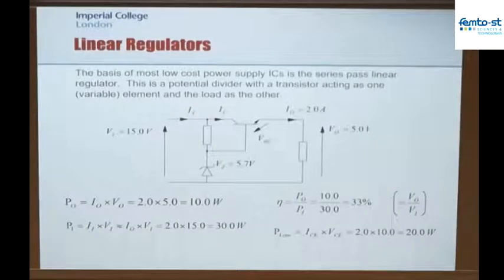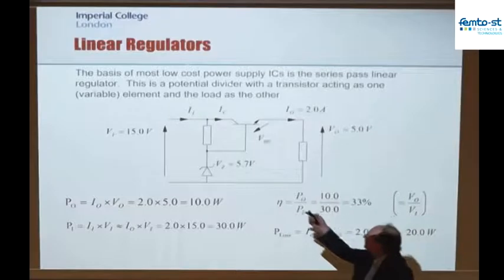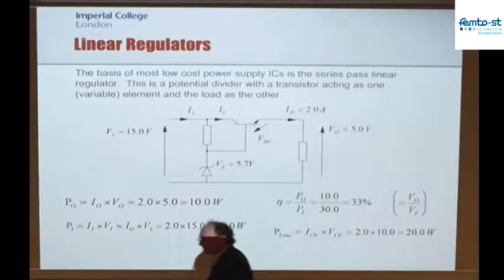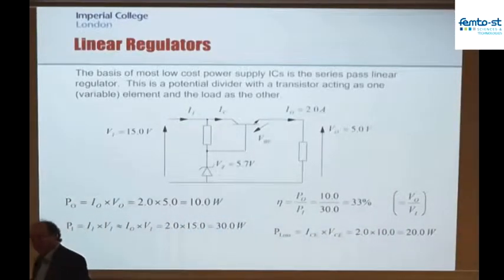So this circuit here is what we would call a linear regulator. And if you look at data sheets for electronics, if you build a piece of electronics, you'll see this. If you look at RS or Farnell or Mouser or DigiKey, wherever you buy your electronic components from, you'll find big sections in their catalog for linear regulators. But there is a fundamental problem with this. If you do 15 to 5 volts, you've only got 5 divided by 15 times 100 of the efficiency.